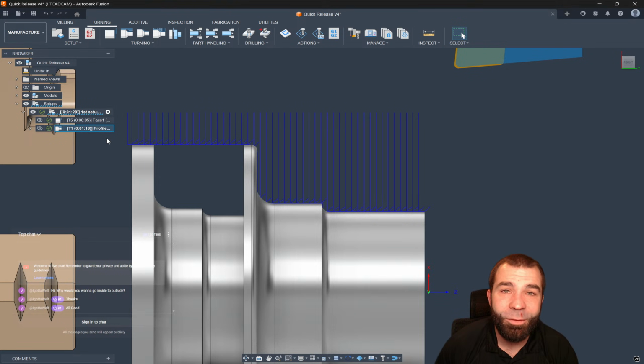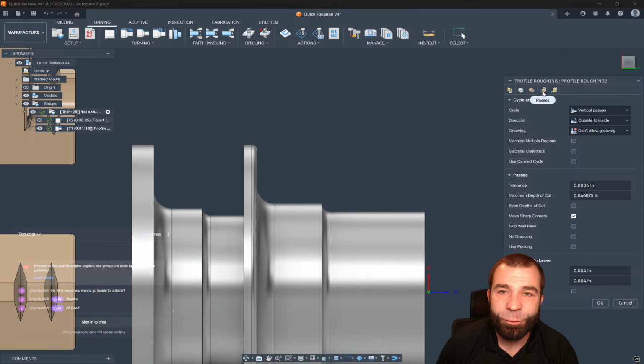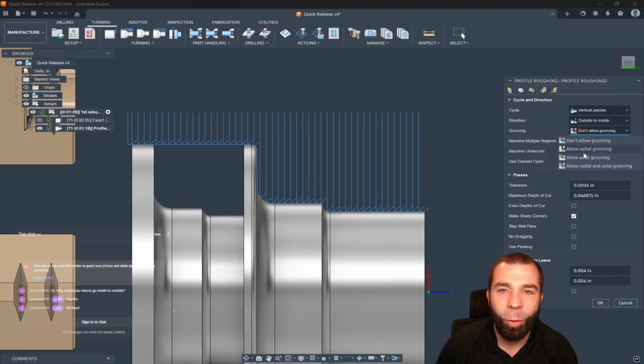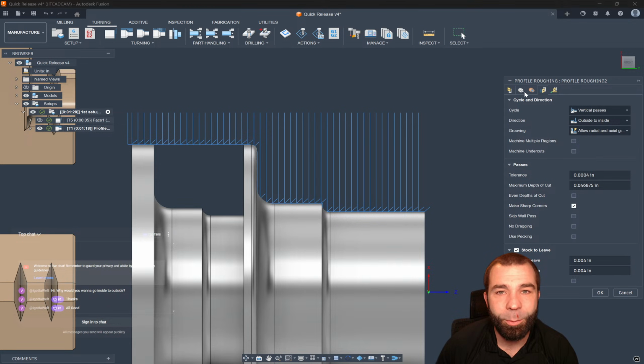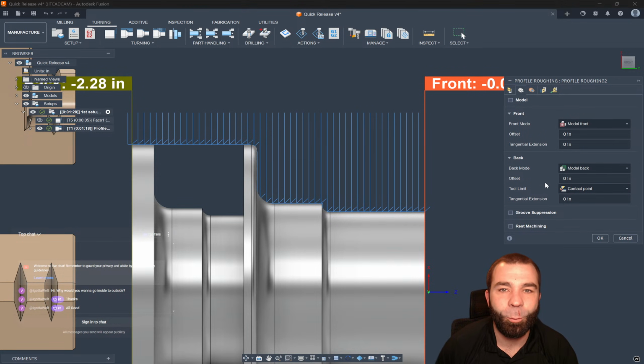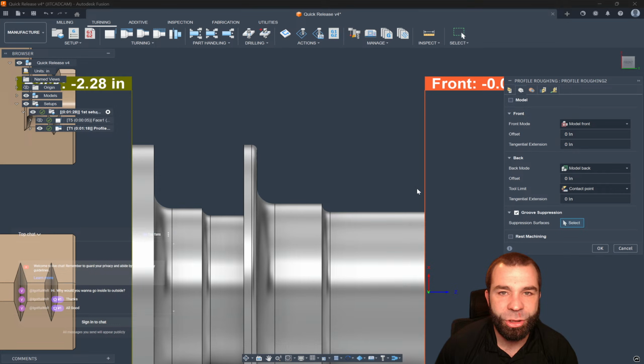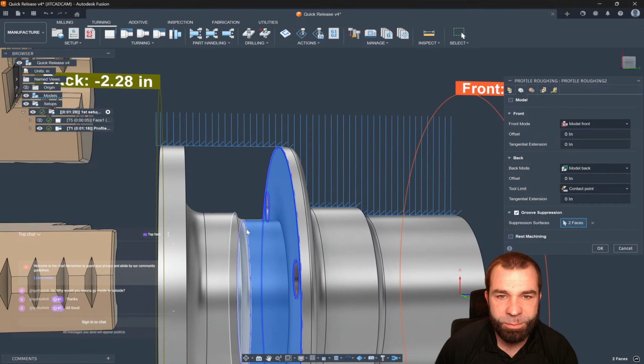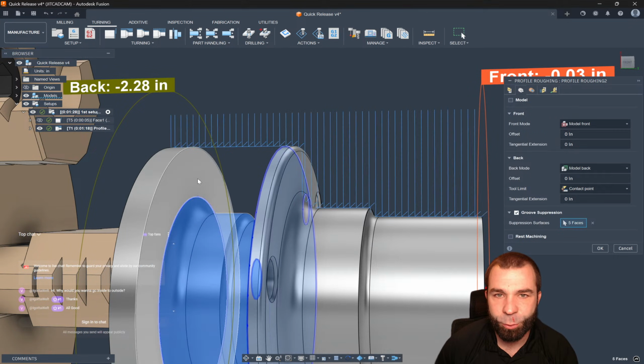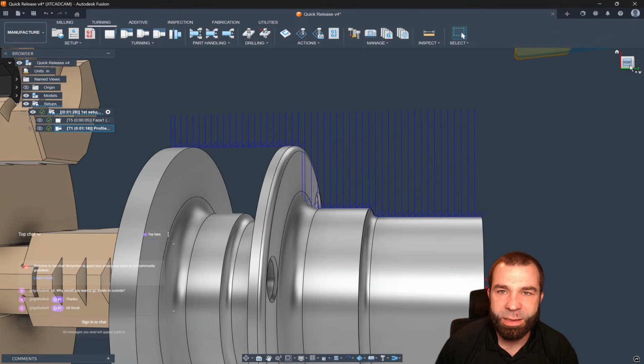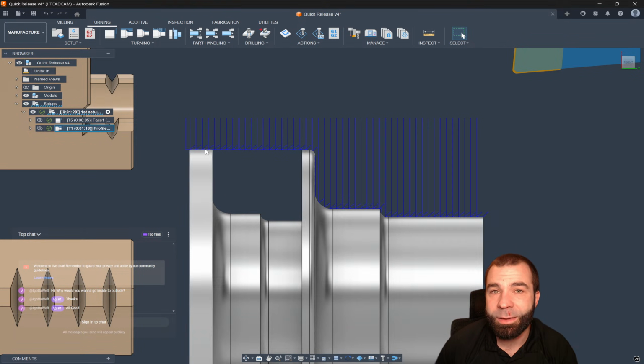If you've caught my video last week, actually 2 weeks ago, the correct way to fix this, which is why I always go back to rule number 1, is we should have fixed it when defining our geometry. I should have said groove suppression, don't go in this groove. And as you guys are going to see, we'll no longer be going inside that groove.